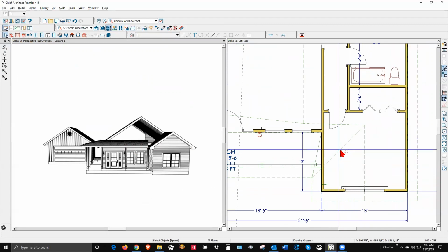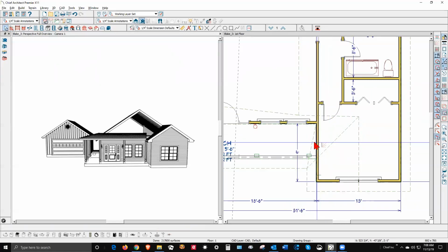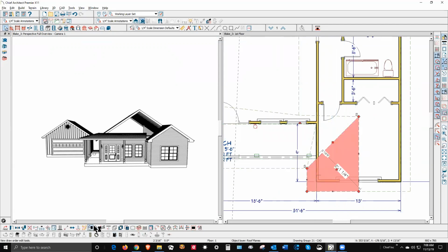You can see that the edge of this roof here is at a 45-degree angle. And that's when it was auto-generated. This one was at the same pitch, 8/12, and this is 8/12. And when they mate, they would create, by simple geometric factors, a 45-degree angle, but a 3/12 and an 8/12 will not. So I'm going to take this roof plane and alter its edge.